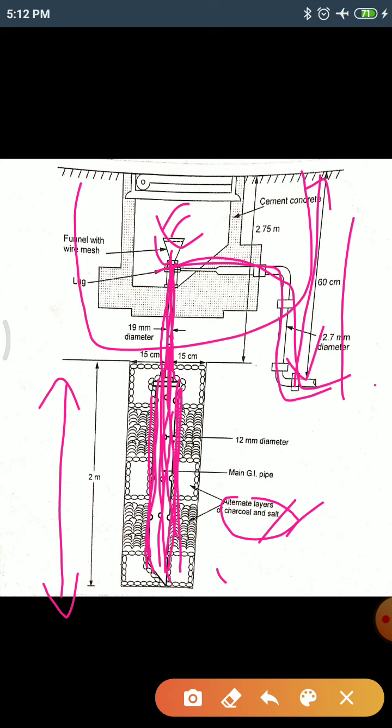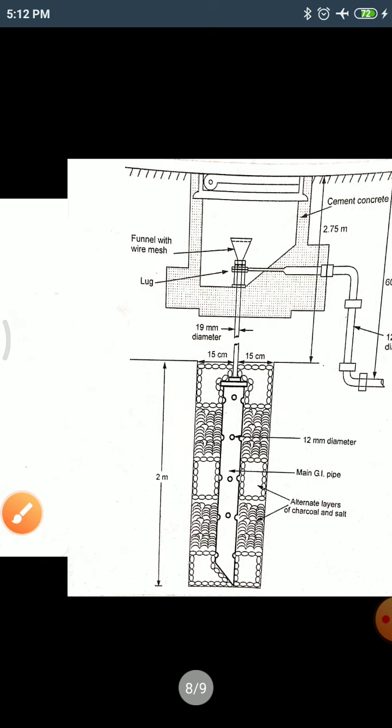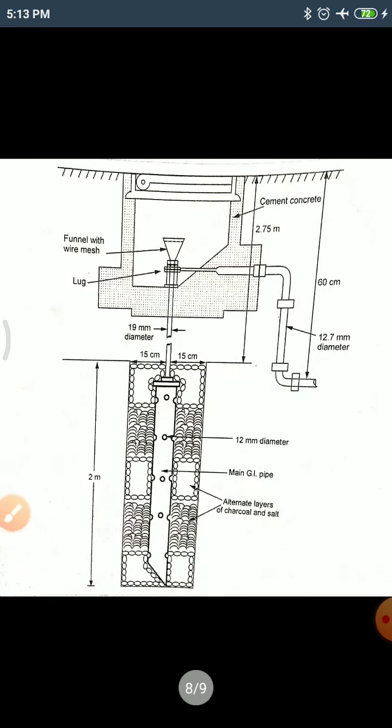One more thing, the only disadvantage of pipe earthing is that the embedded pipe length has to be increased sufficiently if the soil specific resistivity is high. This increases excavation work and hence the cost. In ordinary soil condition, the earth resistance should be 2 to 5 ohms. You would have seen this 5 ohm earth resistance in the earth resistance test using a megger in the lab. These two are your earthings, plate earthing and pipe earthing.